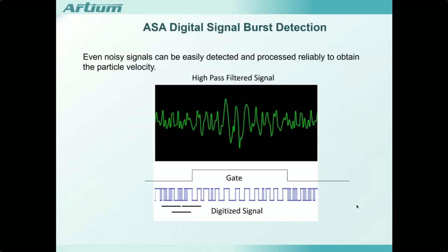The higher level processing then analyzes that signal and determines if it meets certain validation criteria. If it doesn't, it's rejected. But typically, the discrete Fourier transform is very effective in hunting down, analyzing and extracting frequency from noise. And so the detection means has been an amazing advance for LDV.